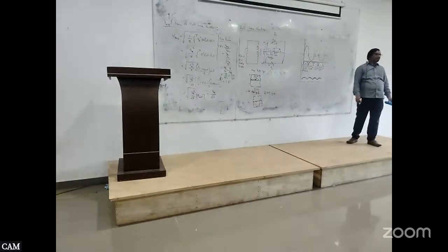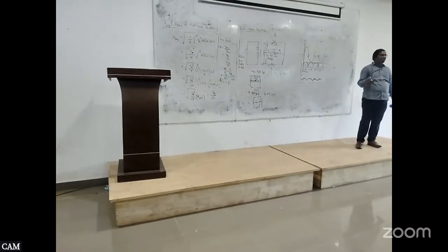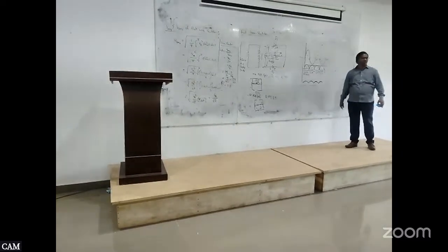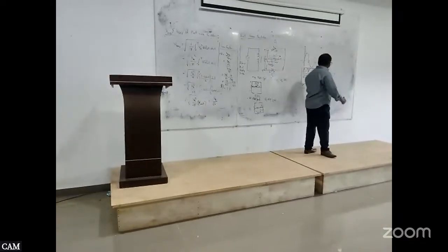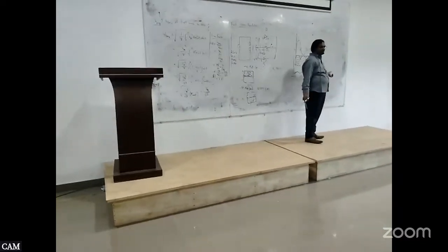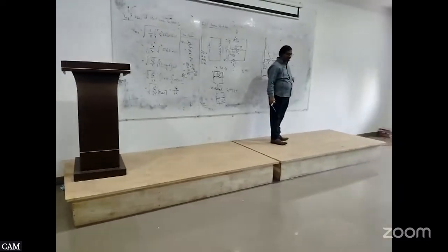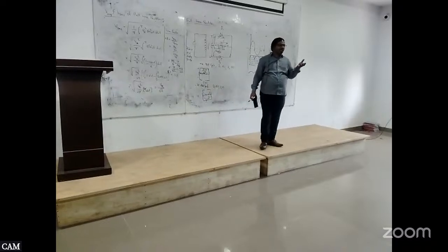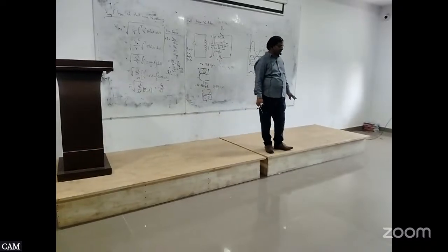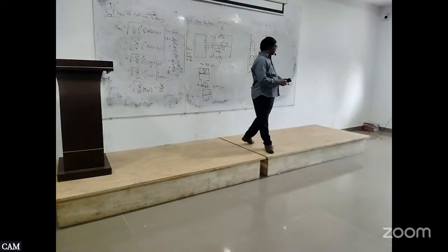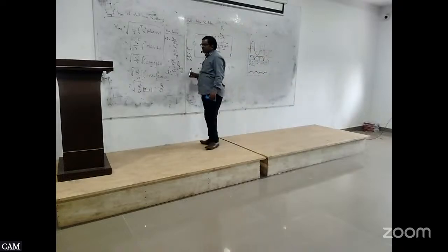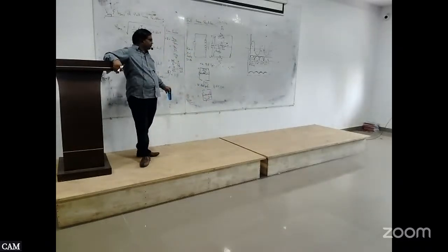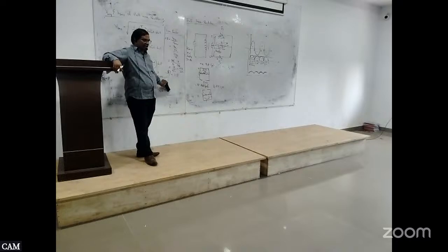By adding a good capacitor, by adding a good filter, this curve will become like this. We can say it is, not exactly but approximately, a straight line. Yes, it is a straight line. So now we converted AC to DC. Okay, this is about the half wave rectifier and the full wave rectifier. So we may expect this full wave rectifier in the exam.